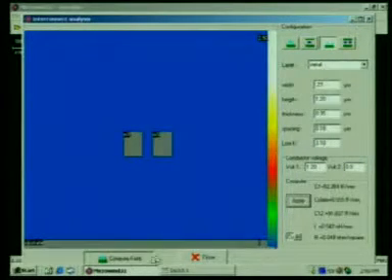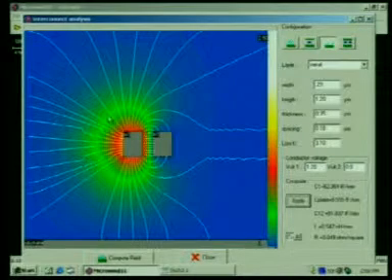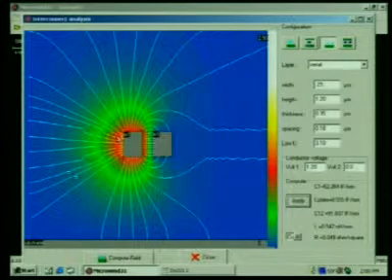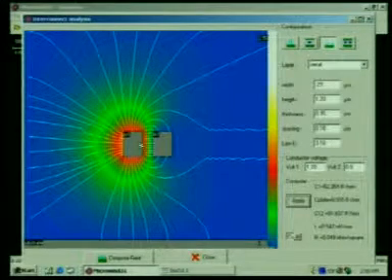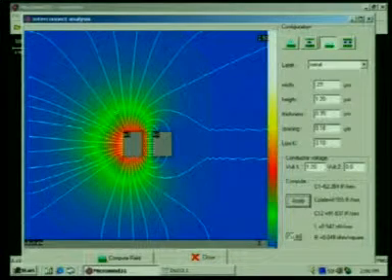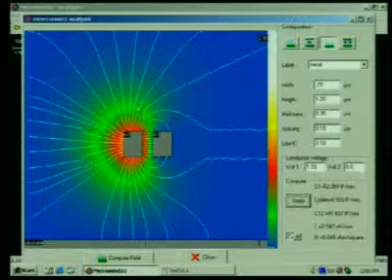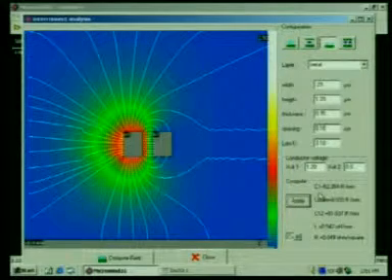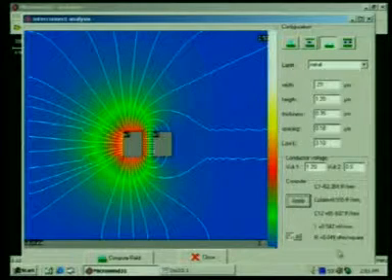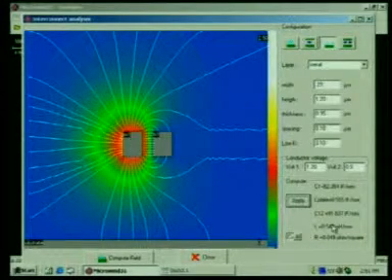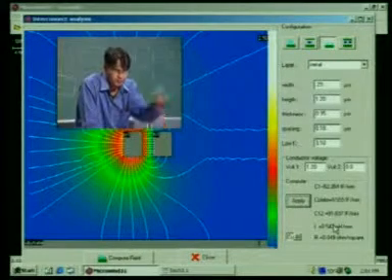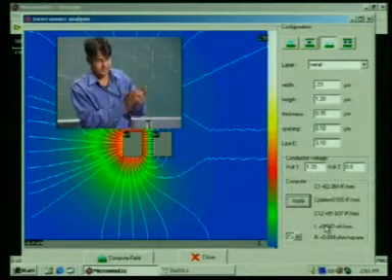Still, we are using these two metal layers for interconnection. After that I will ask for compute field. This means the expert designer can analyze properly what the electromagnetic effect should be, and there will be automatically generated data, like all the capacitance, inductance and resistance values here. So after analysis we will finally go for this kind of interconnect, with proper analysis of that interconnect.